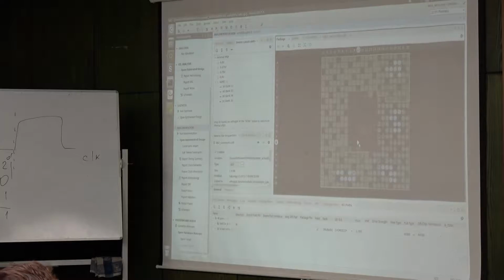If you are using the Z-board, you will see that next to each diode or each slide switch or push button, you will see the corresponding chip pin code. So there is a routing from, let's say, your slide switch to the chip, and you can see the number of the corresponding pin on the Z-board. And what you do, you go down here in order to find your circuit.